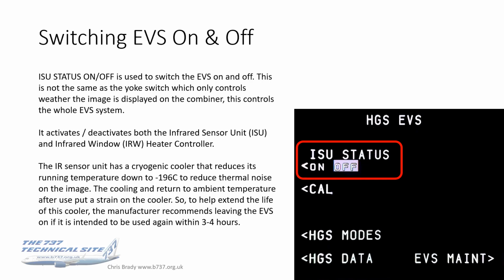Now, that cooling process and return to ambient temperature after use put a strain on the cooler and the components within it. I mean, you can imagine most things, if they cool down to minus 196 degrees centigrade, would get fairly brittle after a few cycles. So to help extend the life of the cooler and the components, the manufacturer recommends leaving the EVS on if it's intended to be used again within 3 to 4 hours. So that's just about being kind to your equipment.